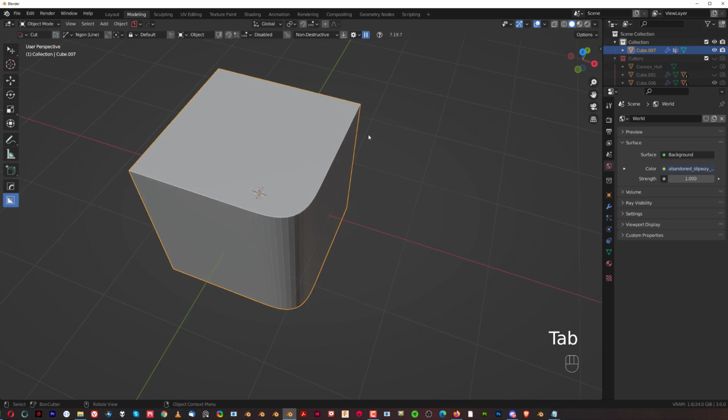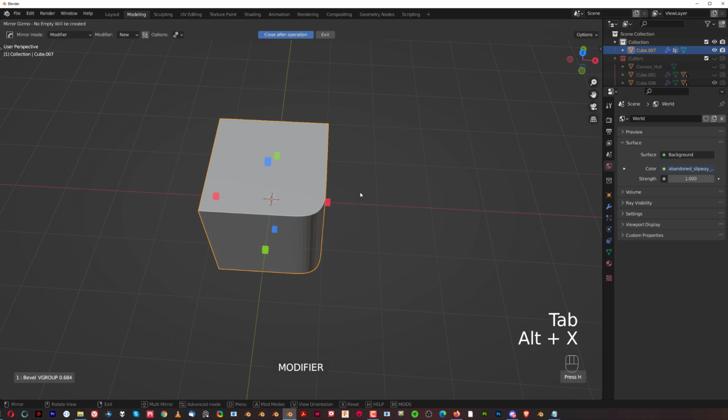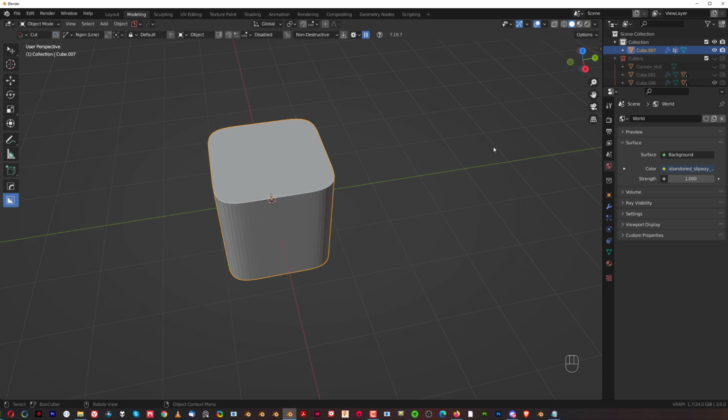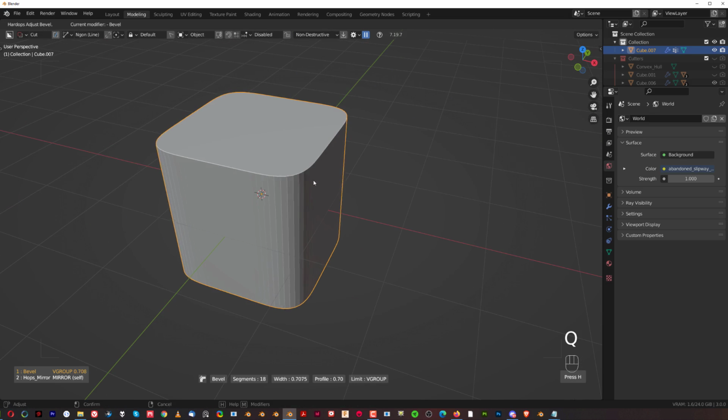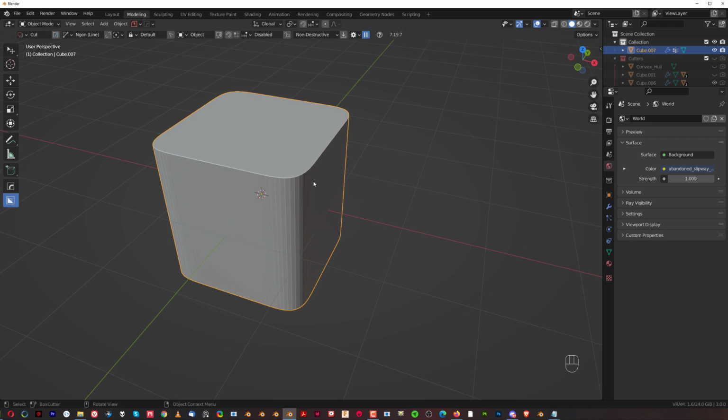And in addition to that, I can mirror this bevel, holding Shift, on both axes. And now I've got bevel running on this cube, okay? And it's all live bevel, and it's being mirrored. Really cool stuff. Very useful when you want to add bevel just to one edge.